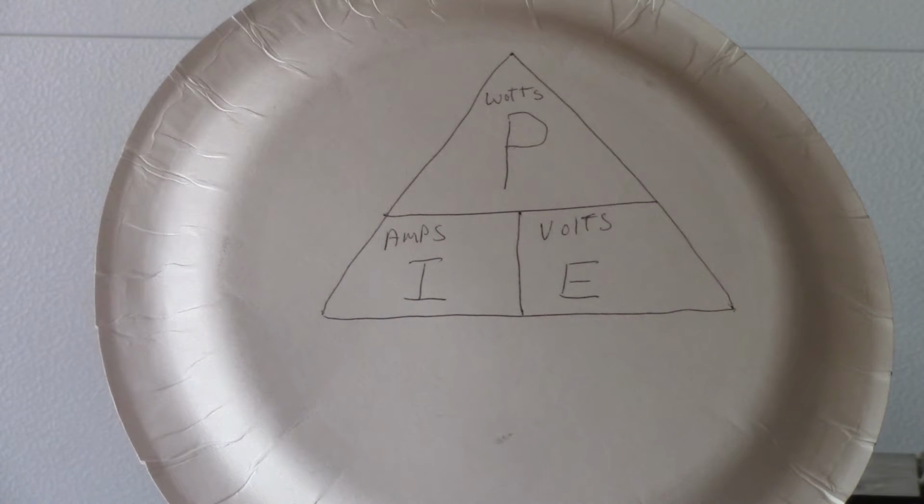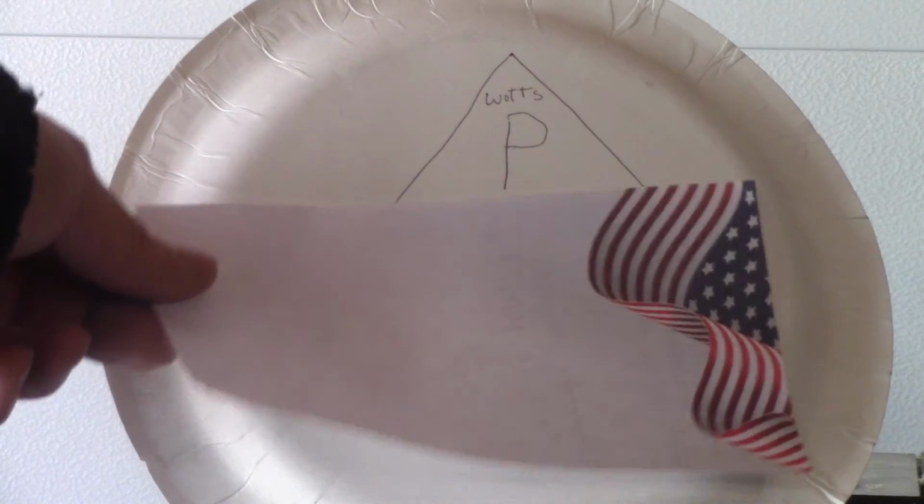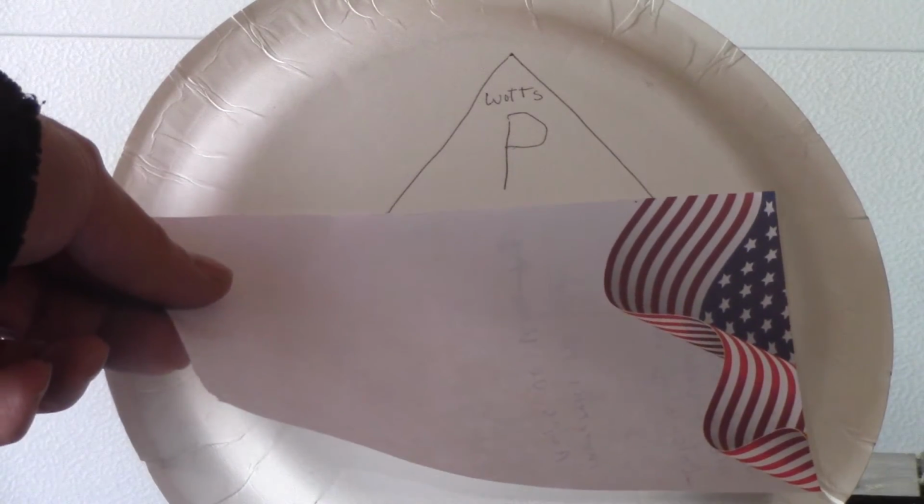Now why do we want to know P or watts? Because more and more circuits, or potential, or draw, is being shown in watts, like LEDs, right? If you want to run, say, 6 10-watt LED lights, that's 60 watts, right? So you know watts. You've got 60 total is what you're going to want to run.